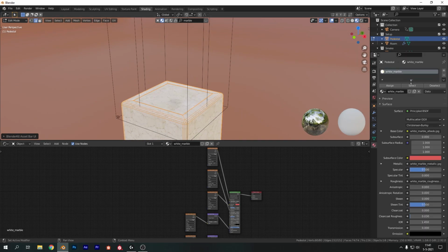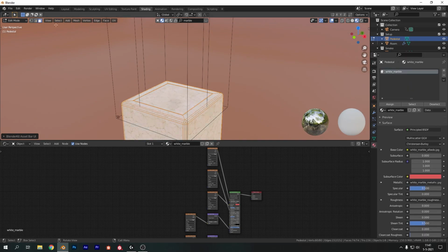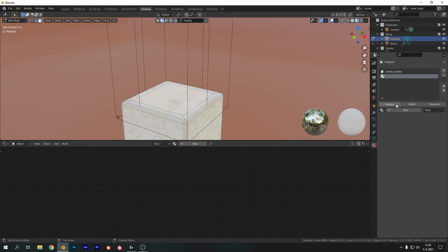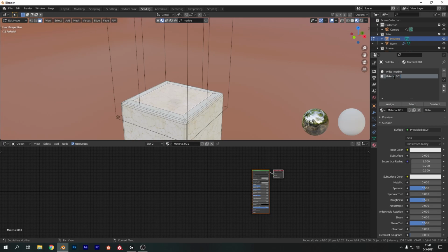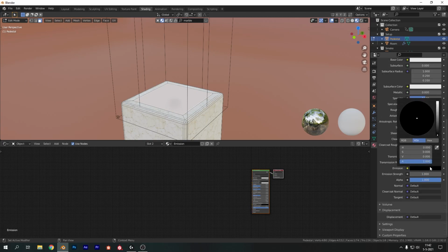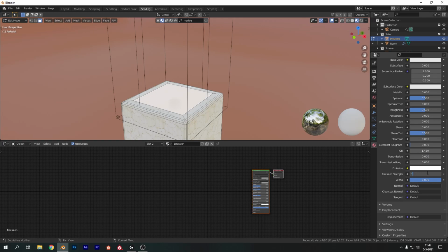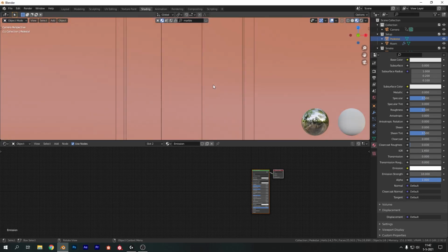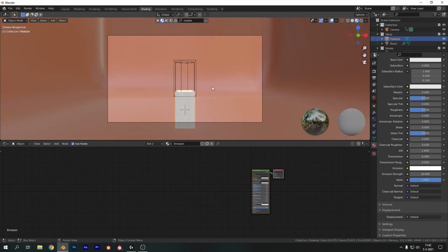And I want to add in a second material. So let's go into the material menu on the right side there. Select the face on the interior there. Add a new material and let's call it emission, and make sure to hit assign so it actually applies the material there. Now we can crank up our emission from black to white and increase the strength to something like 10, which will give us a nice bottom light lighting our smoke from below.